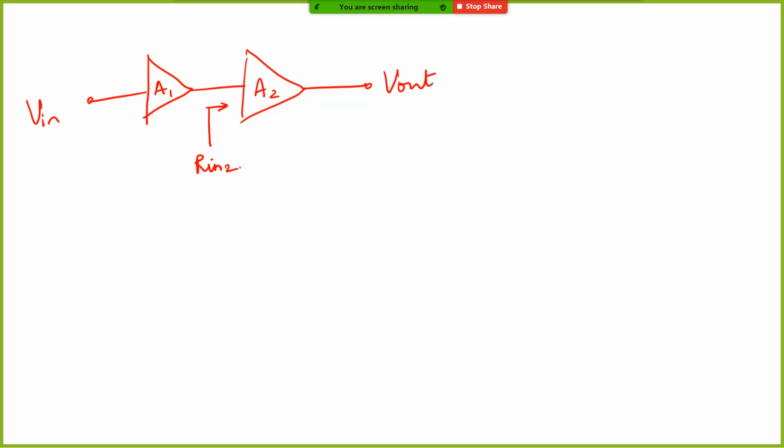So when you are designing A1, you should be able to know what will be the gain. Let's say you're designing two amplifiers, putting both of them in cascade, and you want an overall gain of some 50 dB or 60 dB. 60 dB gain is a gain of 1000, right? So suppose you want to put two amplifiers in cascade.